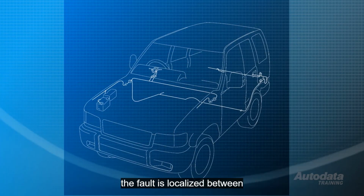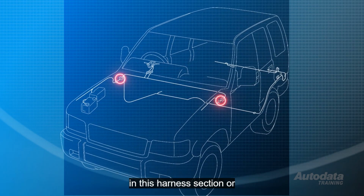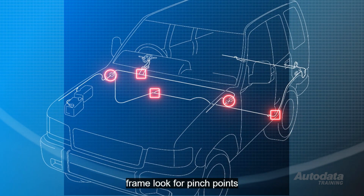If the fault is localised between two connectors, focus on any splice joints in this harness section, or points where the wiring passes through a firewall or door frame. Look for pinch points or evidence of accident repair.